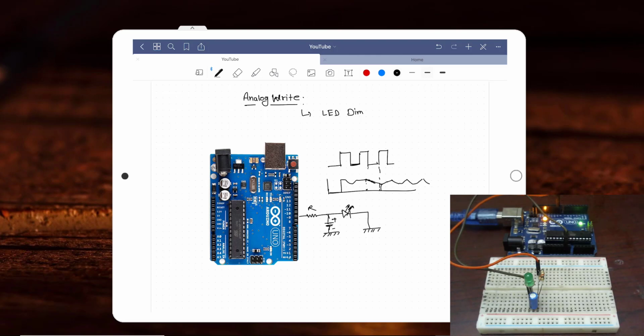Moreover, with the capacitor we can regulate DC voltage, with some duty cycle. So what is the duty cycle? Let's say this is on time and this is off time. So the duty cycle, D, is the on time divided by the total of on time and off time. This is the duty cycle. So the higher the duty cycle, the higher the voltage. Let's say this is V, the voltage is higher if the duty cycle is high.